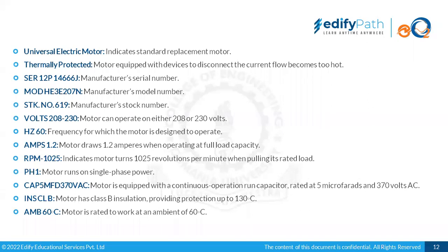The motor is equipped with a continuous operation run capacitor rated at 5 microfarad and 370 volt AC. As we see that this is a single phase motor, we would be using a capacitor to run this motor. So this would be the basic identification of the capacitor that is being installed for this motor.